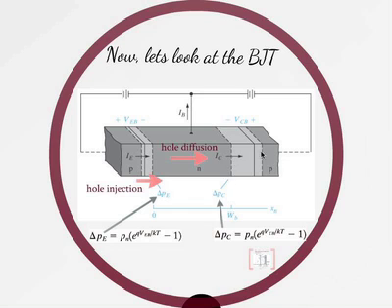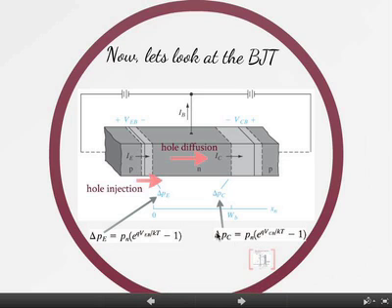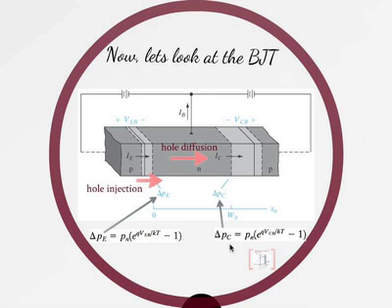So because the junction is reverse biased, of course you would expect carrier extraction on that side, and the excess hole concentration at that interface should be quite a bit smaller than the equilibrium concentration of holes, right? VCB is negative, so this whole thing is very small. In other words, this delta PC is negative, which means you have lost holes on that side. Which of course makes sense. It's a reverse bias junction, right? It'll pull those holes out. Okay, carrier extraction, which is what we had in our midterm.